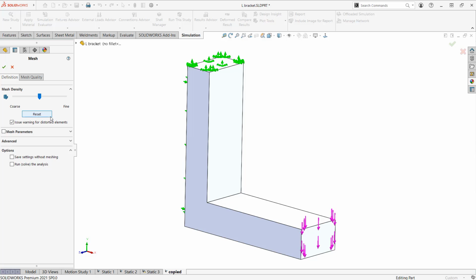This is unique to every single model. Fine means something for only this model, and coarse means something only for this model. The next time you load a different model, fine and coarse will mean different things. There'll be different sizes. This is all based on the overall shape and size of your model with an algorithm that looks at the geometry itself. So this is not always 10 and 1 and 100, right? It's unique to every single model.